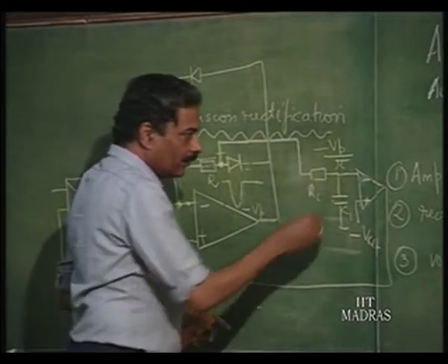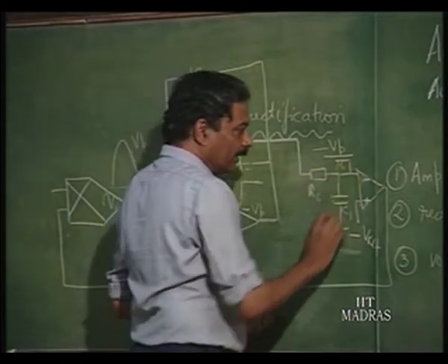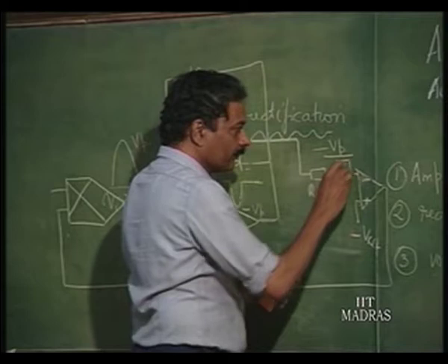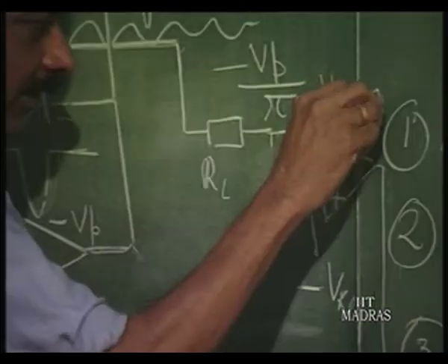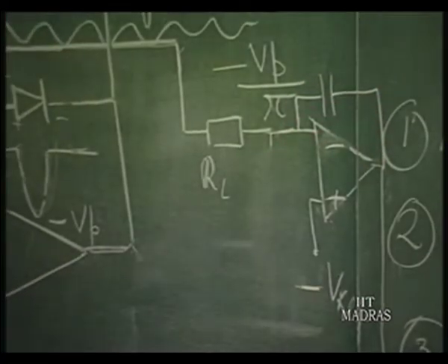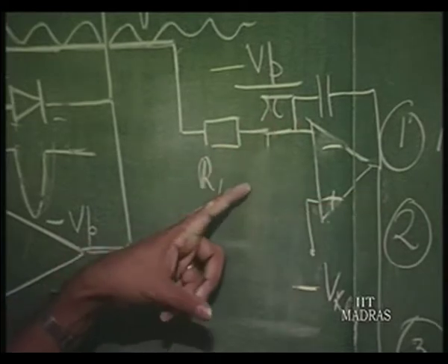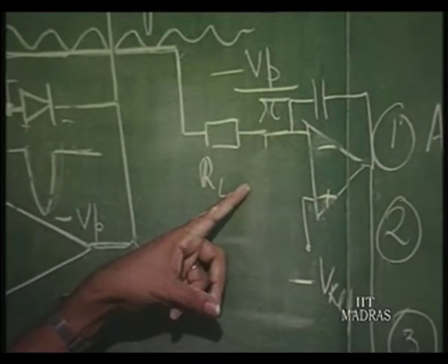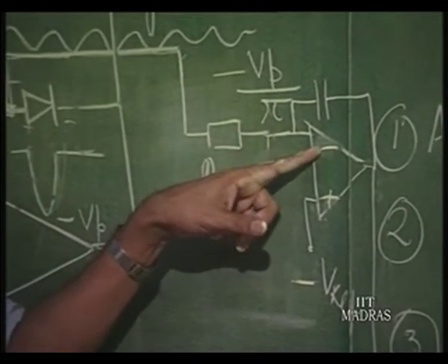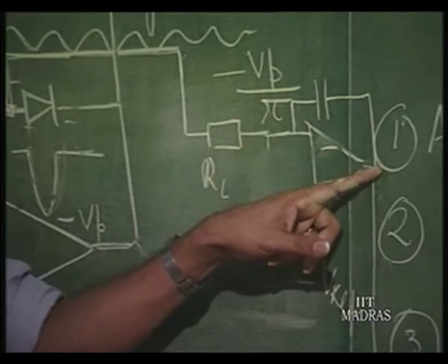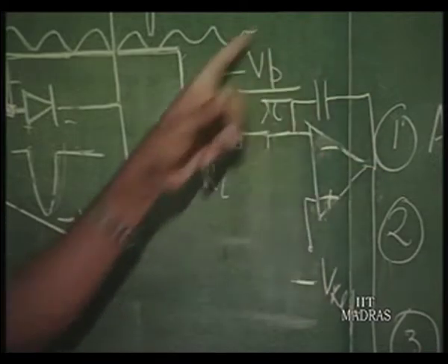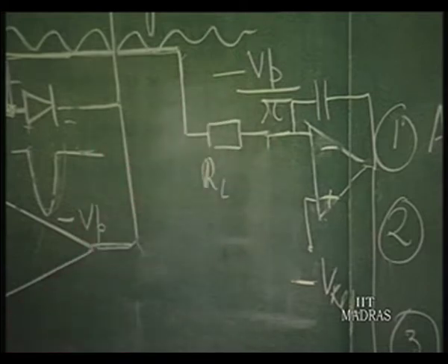So, then I can put this capacitor as a feedback capacitor. This is called Miller effect, that also I have discussed earlier. So, this capacitor appears as a huge capacitor at this input. That is possible only if this is negative, because this has to give negative feedback. Okay. So, this controller now becomes this way.